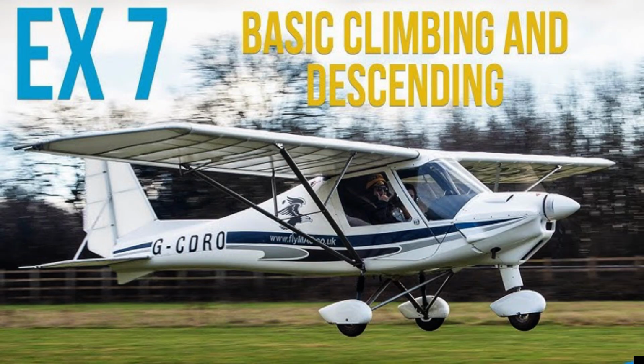Climbing and descending en route. When ATC issues a clearance or instruction, pilots are expected to execute its provisions upon receipt. In some cases, ATC includes words that modify their expectation. For example, the word immediately in a clearance or instruction is used to impress urgency to avoid an imminent situation, and expeditious compliance is expected and necessary for safety. The addition of a climb point or time restriction, for example, does not authorize pilots to deviate from the route of flight or any other provision of the ATC clearance.